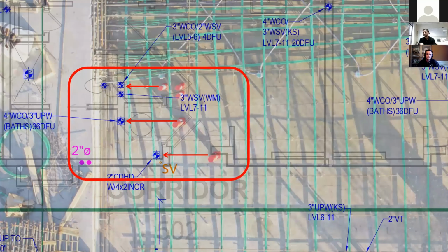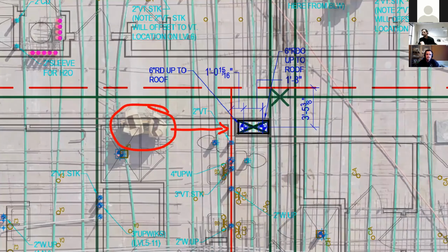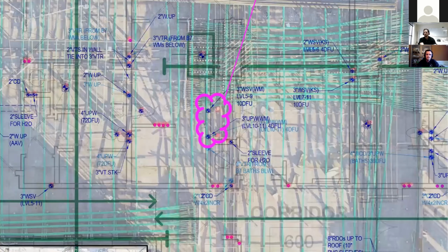So these are just a few examples on this one project we picked out. In this bathroom, there was a control that somebody knocked over with their foot and set back 5 feet in the wrong direction, so they actually pulled tape off wrong. We caught that before it got installed. Some shafts are just installed in wrong locations. And if some sleeves are off a few inches, I can kind of see it. And then it's just that relationship with the guys in the field to back check.